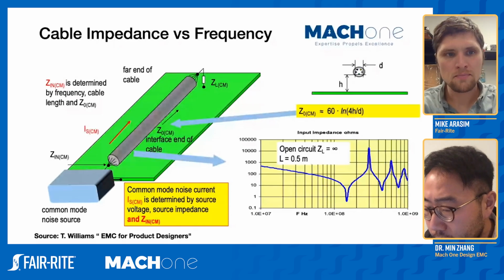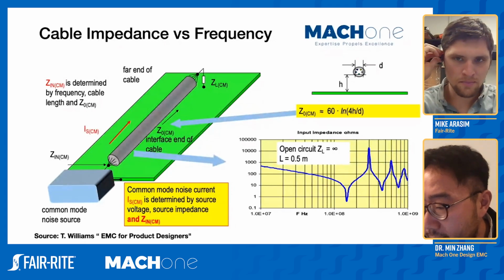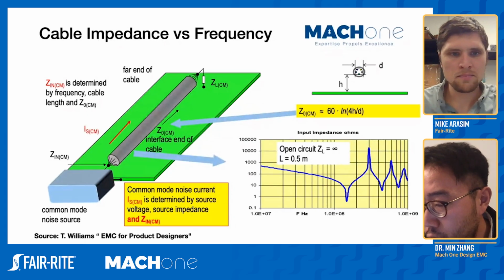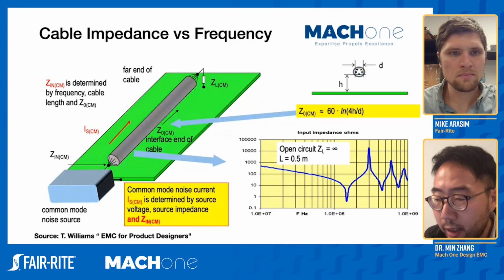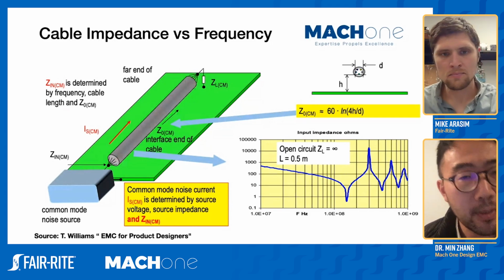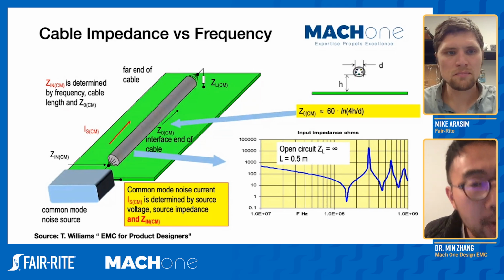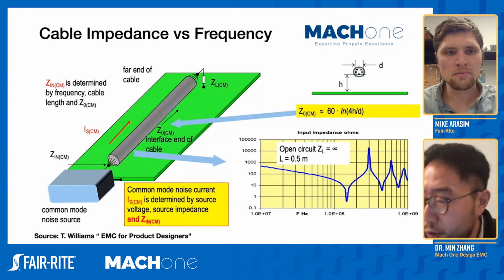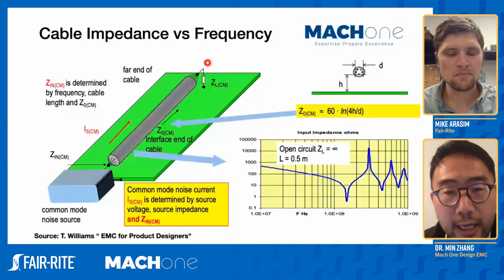They will resonate against the frequency. So here we wanted to demonstrate this by having these slides. As you can see, this cable bundle shown here can be shielded or non-shielded, but regardless, when we talk about termination impedance, we are talking about the common mode termination. For example, in this case, the ZL represents the load termination, which is a common mode connection.